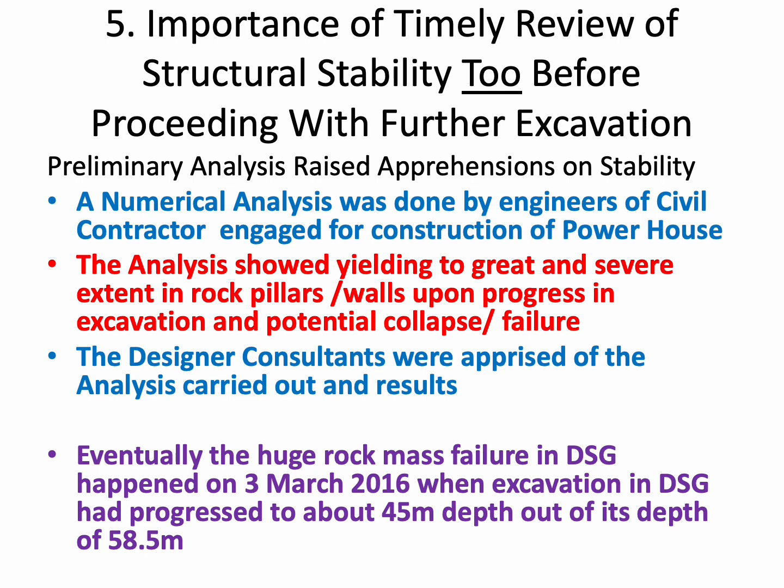A numerical analysis was done not by the designer but by the engineers of the civil contractor engaged for construction of the powerhouse. The analysis showed yielding to a great and severe extent in rock pillars and oblique walls upon progress in excavation, and potential collapse, oblique failure. The designer consultants were apprised of the analysis carried out and the results.